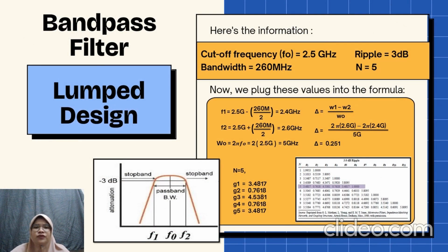Lumped elements for integrated circuit and inductor capacitor for microcircuit and board application. It also involves lumped element design and distributed element design. An electronic filter with a distributed element design does not contain discrete components for capacitance, inductance, and resistance. Lumped element filters have two types, which are T-network design using series elements, while pi-network design uses shunt elements. T-network is recommended for even order filters, while pi-network is for odd order filters.